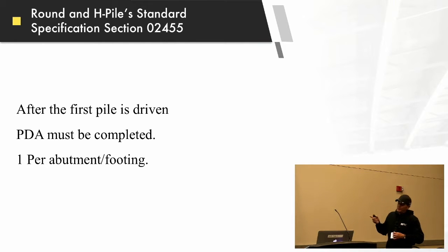But as you're doing the PDA, for me, I've always liked to be right there with the geotechs when they set their sensors, help count the blows per inch for them. And then what's really good now is with the technology we have now, most of the time they can calculate that right on site and give you a driving criteria, and then you can just continue on.